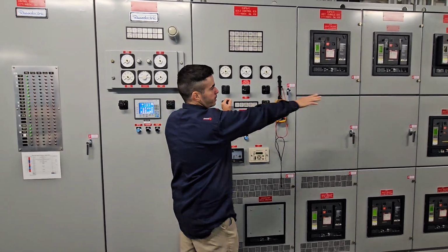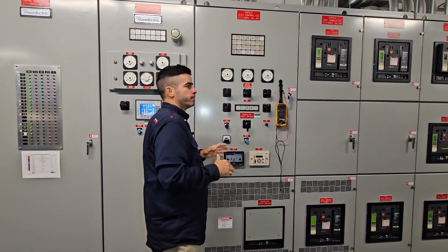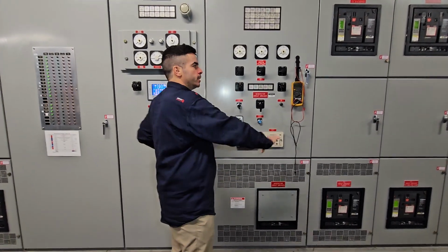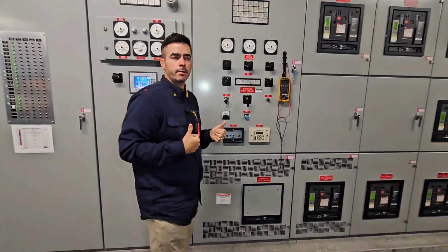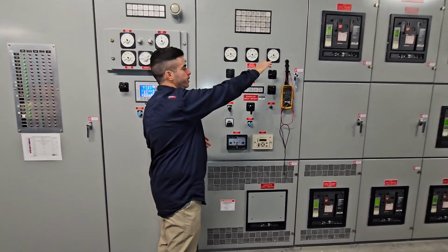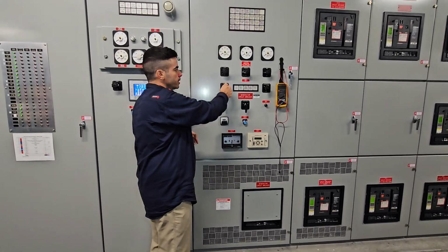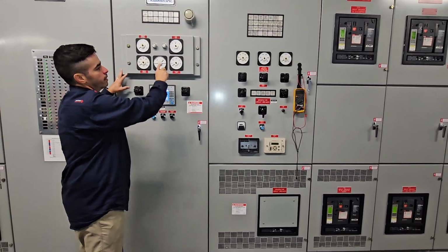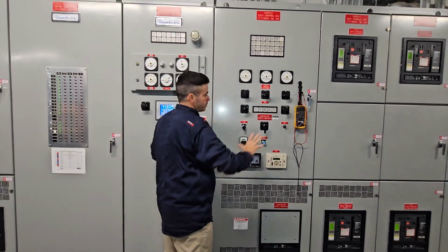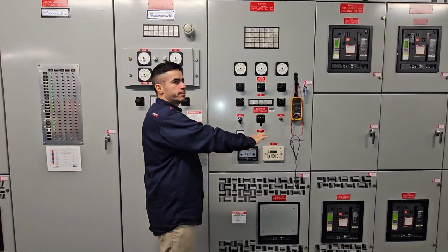So we only have one set because we can only close one breaker at a time if we're in manual, right? So if we are closing the breaker to that bus, like it's the first generator that is going to come online, then as long as we have good voltage, 480, 60 hertz, and the generator is already running, we turn on the synchroscope. For the first one, you won't see a difference here, but as long as all those conditions are met, you can just close, and the breaker should close, and then you have one generator on the bus.